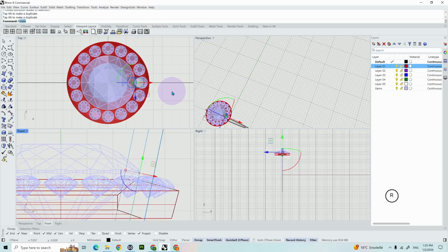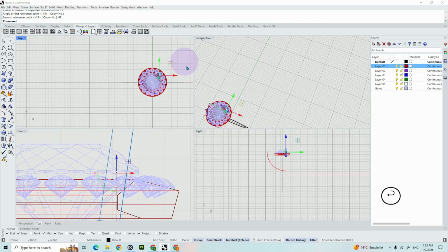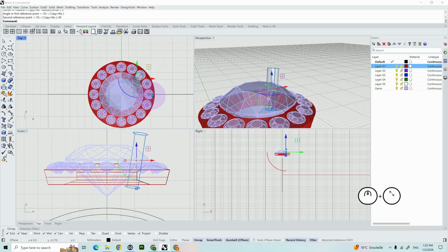Then I'm going to use the rotate command, center of the rotation, type 0 on your keyboard, snap it on this horizontal line, and hold shift to position at a 45-degree angle, or simply type 45 degrees on your keyboard and press enter, just like so. Once it is done, I'm simply going to mirror this on the sides that are missing.